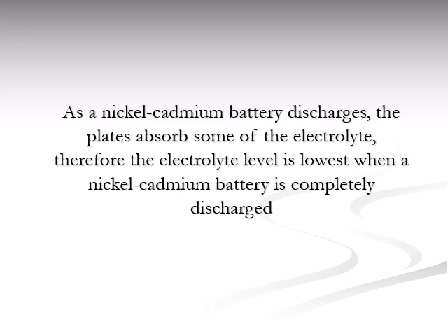During discharge, the plates absorb electrolyte, lowering the level. After charging, the electrolyte level rises. Always check levels after full charge.